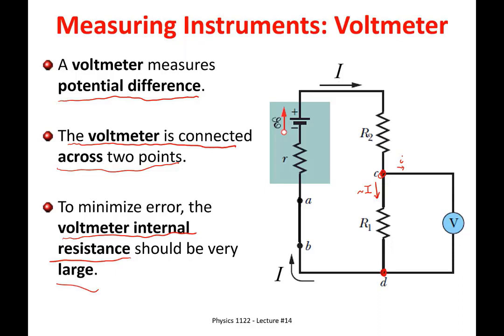So always when you are using measurements in a circuit, if the internal resistances of the measuring devices are comparable to the resistances in the circuit, then you have to recognize that you might be disrupting the circuit itself just by attaching the measuring device. And that's all I really want to say about these two topics.